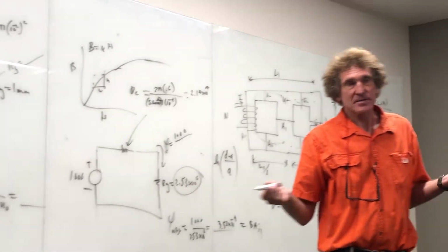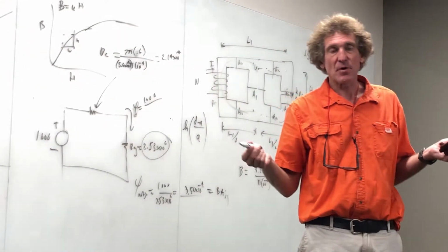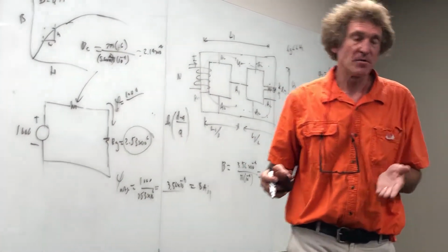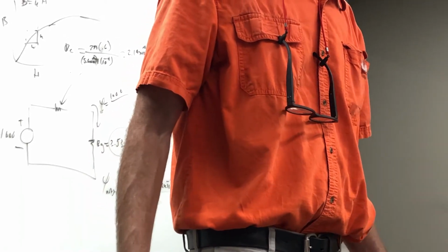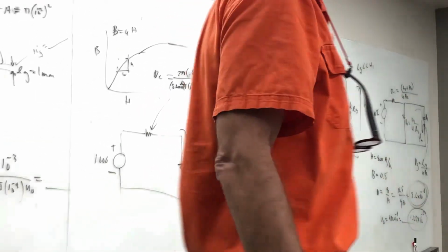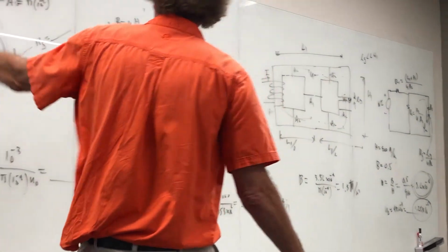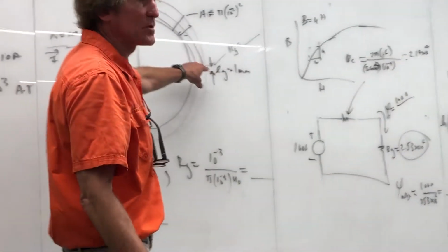That's the way you do these things, but it's a nonlinear problem, and that's the problem. He doesn't give you a mathematical equation for us to use. He just gives you a curve. Have you done nonlinear solutions before? Usually you start at the extreme. Get rid of the core material entirely and find out what the B field would be.